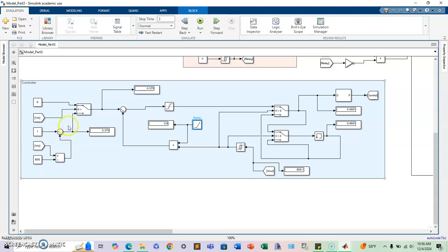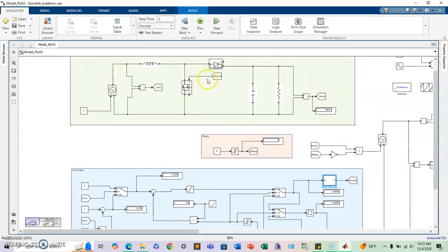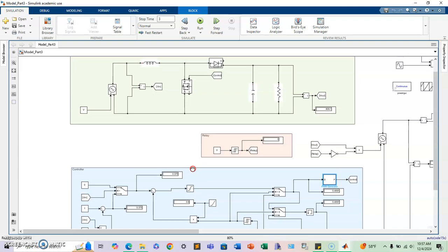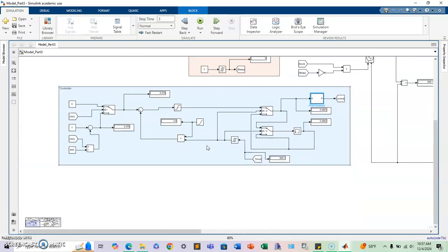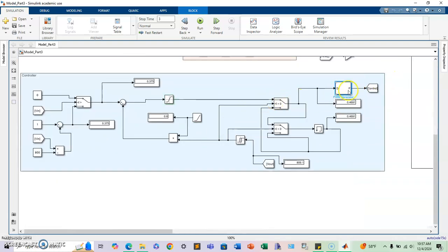What this does is it analyzes the amplitude voltage and determines the starting point. So we can start either from 0 or do an actual calculation to not waste so much time. And what we'll do is add a little bit of the ramp to the amplitude modulation, to the pulse width modulation generator that will go from here to the MOSFET in the boost bus. Once it reaches the parameter that I want, it will stop and latch to the second switch and stay over here.